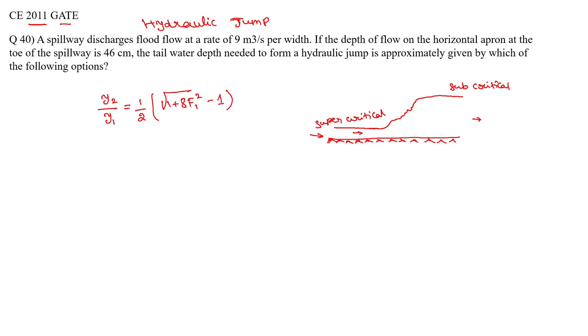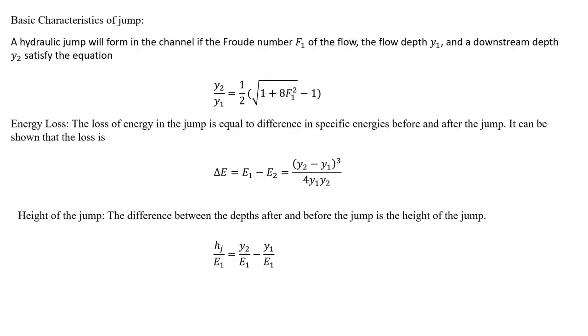And another equation, the energy loss equation: (y1 minus y2) whole cube divided by 4 y1 y2. I hope I'm correct. Anyway, in the next slides I have shown. Yeah, correct. So these are the basic characteristics of the jump we discussed in the previous session.